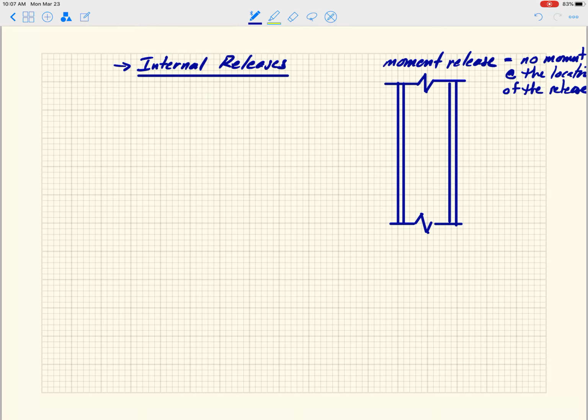So if this is a column, and if I were to flip it up, it would look something like this. Those lines are the flanges of the column. In a lot of cases, and you can see this in Weeks Hall if we ever get back to campus this semester, they shop weld here what they call a shear tab. And that shear tab has a number of holes in it to receive bolts. And then the beam frames in.